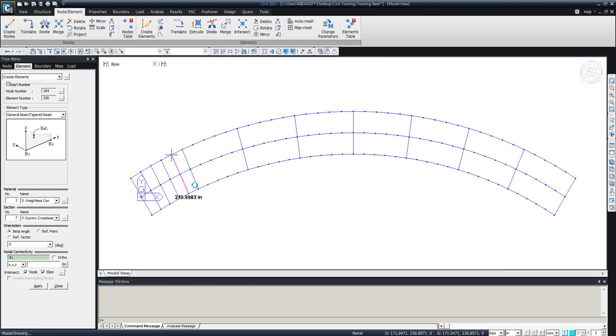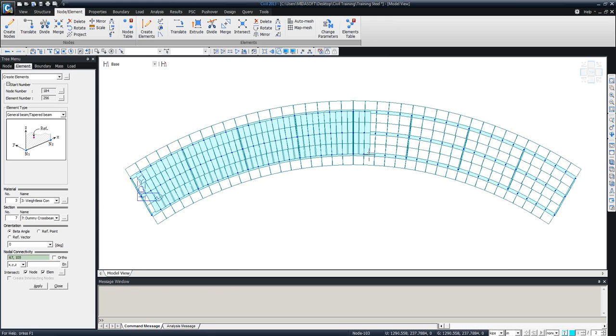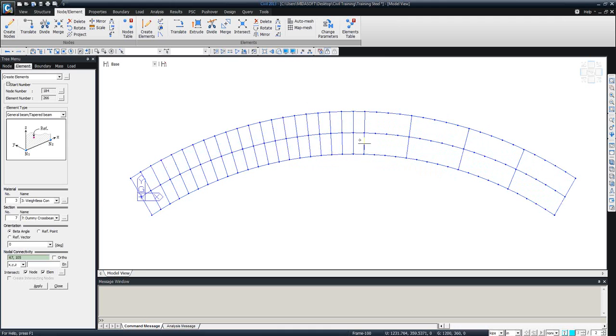And if I turn this on, you can see that they will be covering the entire surface. So for the dummy cross beams, for the thickness of them, we are selecting exactly the same thickness as the concrete has, and then the width of them depends on how you divided these girders. So for example, from here to here is about 2 feet. So this is why I model them as the total width of this slab. These elements are 2 feet. So if I turn this on, you can see that these are covering the entire surface.